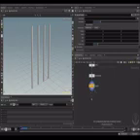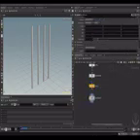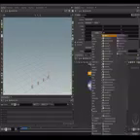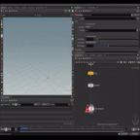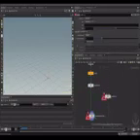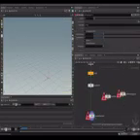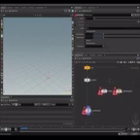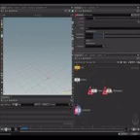To do so, let's fetch a new transform node. Let's set the y scale value to, for example, 0.5. And let's fracture these tiny pieces using a Voronoi fracture. And here, as you remember, you can either use an ISO offset node or a VDB from polygons with VDB. I'm going to use this second option because it's been proved to be faster.